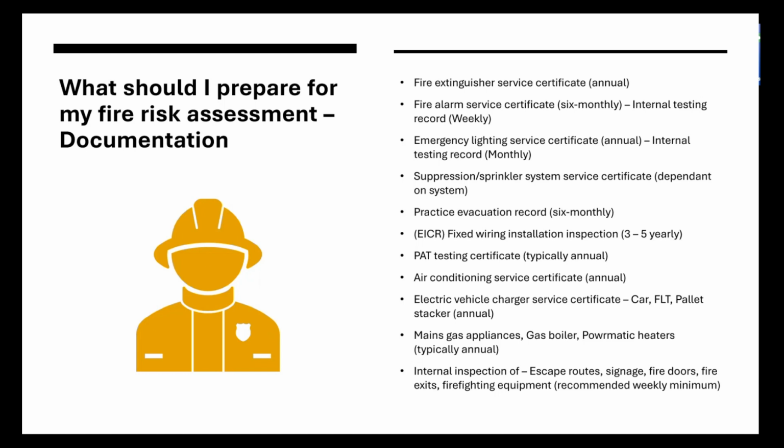So then we move on to mains gas appliances, the gas boiler, Powermatic heaters, which you tend to find in workshops. Powermatic is actually spelt like that as well, so it's not a mistake. There is just no E in there. And they must be serviced by a gas safe registered engineer on an annual basis. They will provide you with a certificate, and you should keep that on record for your fire risk assessment.